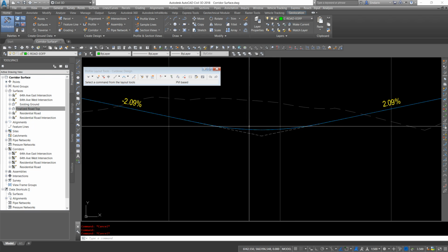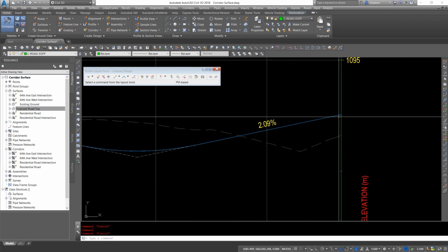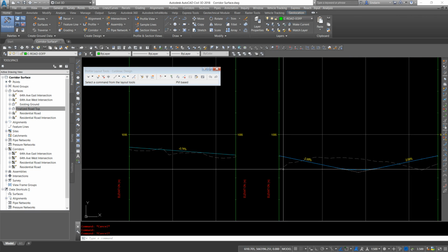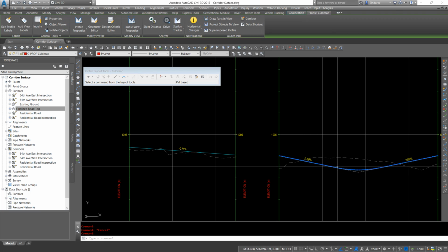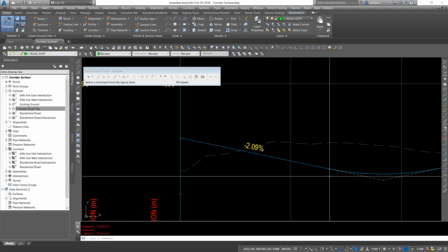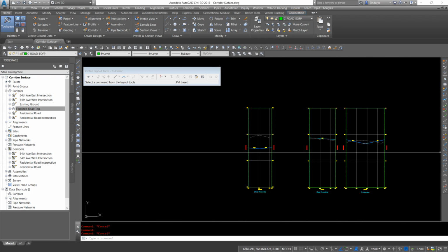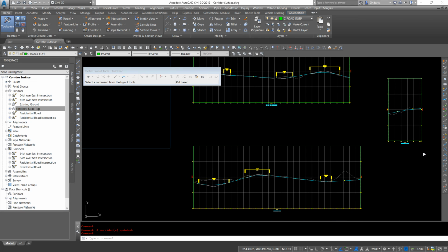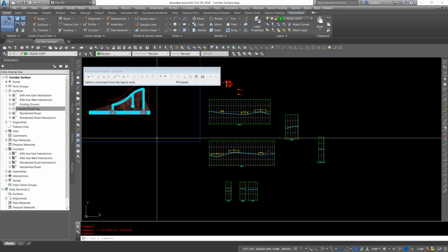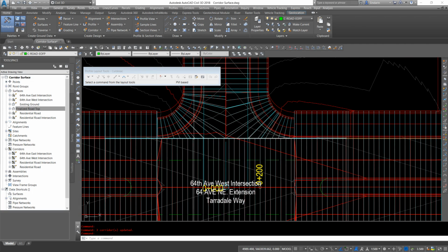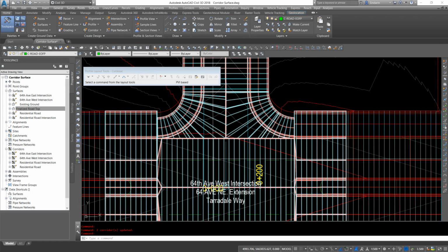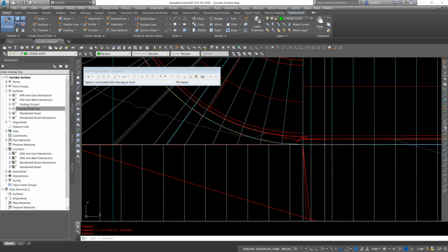Go take a look over here, and our groundwater line should be matching our design line now. So they should be overlaid on top of each other. And again, if you want to delete this groundwater line, go for it. You can also keep it in there to help not confuse you. Okay, so the final thing we need to fix, and we're not going to have time to clean up some of these little triangles, but in the grand scheme of things, that's not a huge issue.